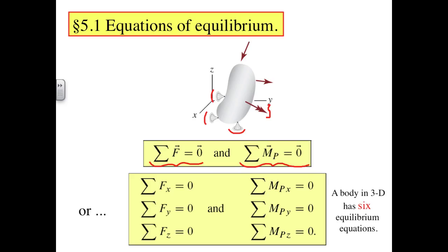What that previous derivation just told us is that if we satisfy moment equilibrium about one point, we satisfy it about every point. You will never generate more information about a single rigid body by taking moments about additional points. There are only 6 independent statements of equilibrium that can be generated for any 3-dimensional body.